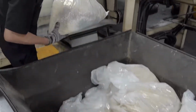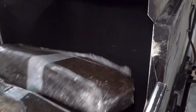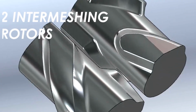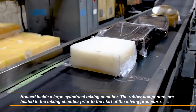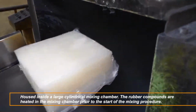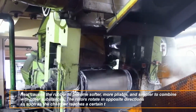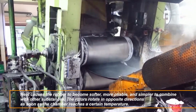Computer systems measure out specific batches of rubber and chemicals and feed them into a Banbury mixer. The Banbury mixer is made up of two intermeshing rotors housed inside a large cylindrical mixing chamber. The rubber compounds are heated in the mixing chamber prior to the start of the mixing procedure. Heat causes the rubber to become softer, more pliable, and simpler to combine with other substances.